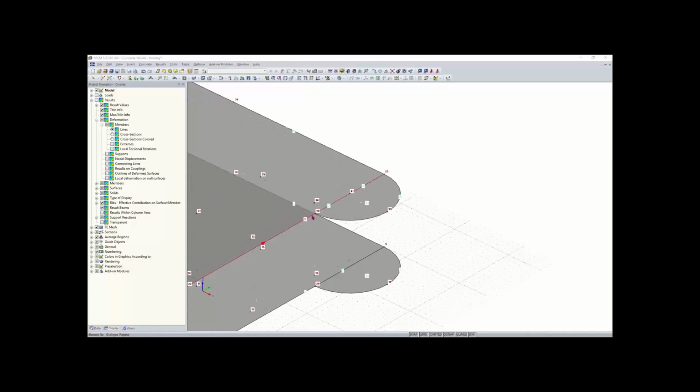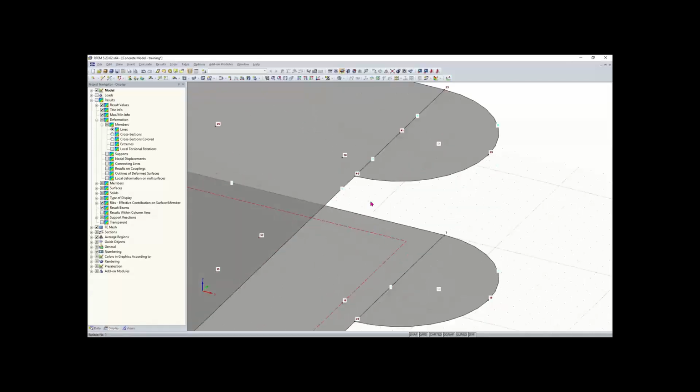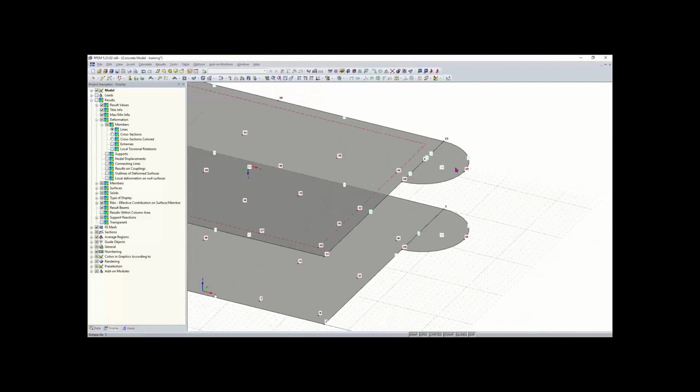And so now, if I want to connect this line to this line at node 40 here, you can see that this line is one whole line. So if I go up here to this tool called connect line/members, I'll click on that and I'll highlight my node there. And you can see that what that did was split that line at that node and connect them, creating two different lines and an intersection. So now we can delete the surface, our top surface here for our ceiling. We'll select the two surfaces by holding Control, delete.